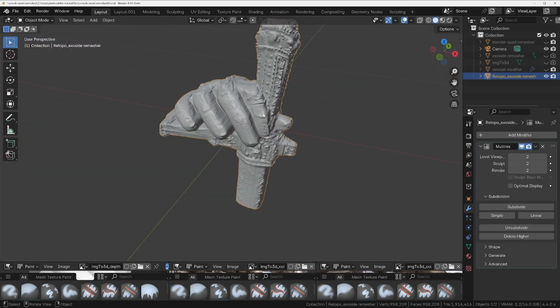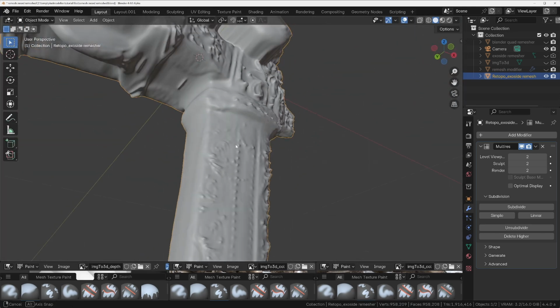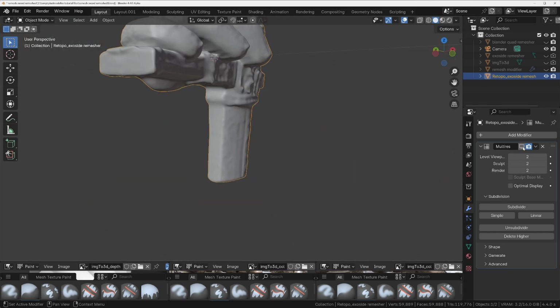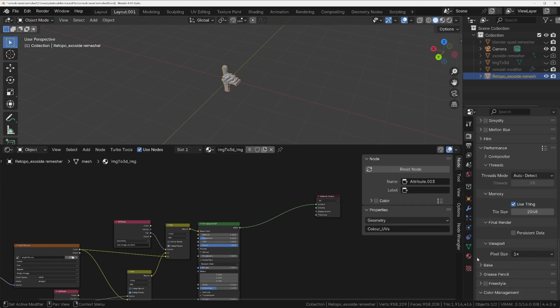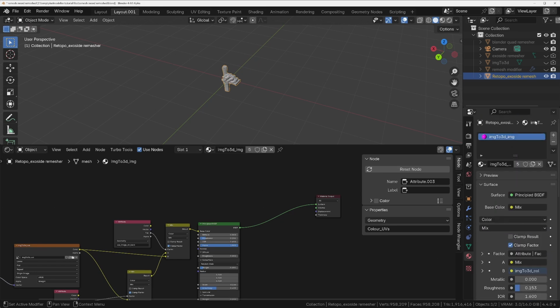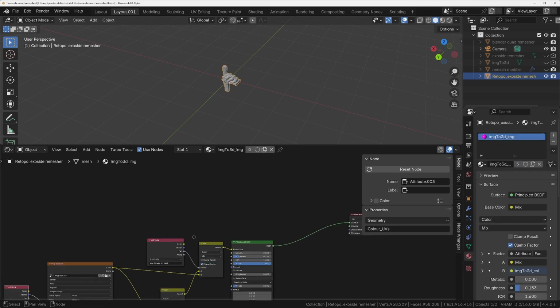Next up, we need to transfer the geometry detail, that fine detail, into a normal map. So that when we've got this turned off and it's completely flat, the render engine, either Eevee or Cycles or your game engine, can recreate these small areas using the normal map. So let's go into the shader editor. Make sure we're using the material in here. So this is the one that's in use.